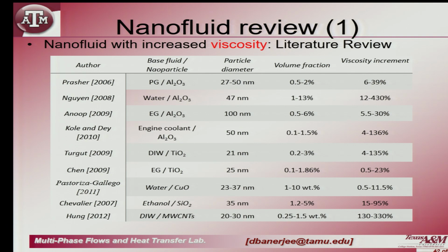So, is it justified to use a nanofluid, when I might get 10% higher heat transfer, but my pump power has gone up by a factor of 10? It does not make sense. My pure fluid for that same pressure drop or for that same pump power will probably give me better cooling, is it not? So, nanofluids are not a universal solution. It depends on the type of nanofluid you are using, and depending on the synthesis protocol you choose, that same nanofluid can have different properties depending on how you are mixing it with the nanoparticles. So, the synthesis protocol is again a very important parameter that people do not pay attention to.